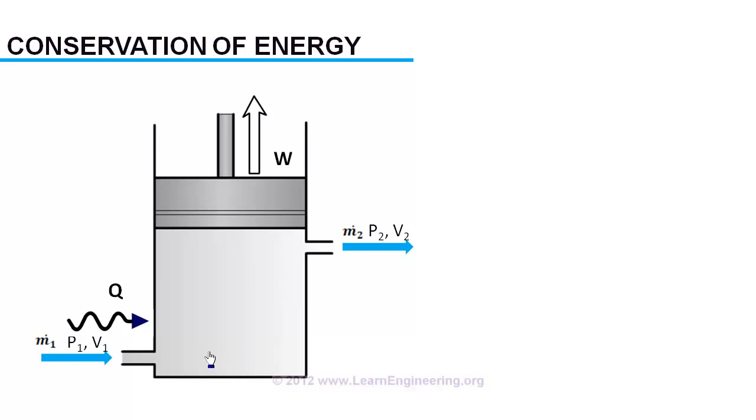So before proceeding to the energy change calculation, we have to define a system first, a control volume, where we will do the energy balance. Here the dotted line represents the control volume, the space in which we will do our energy balance. Here you can see there are 4 energy interactions to the system in total. 2 energy interactions are coming to the system and another 2 are leaving the system. So if you want to find the energy change of the system, you can sum the energy transfer due to these 2 interactions and subtract the energy transfer due to the other 2 interactions.